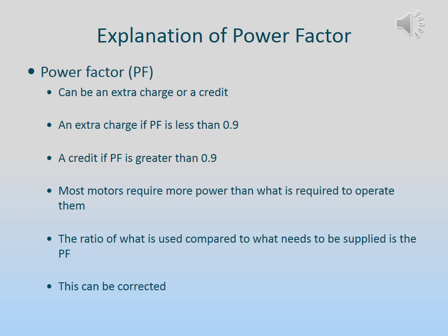Now there is some debate about power factor correction capacitors actually saving money. So let's look at the math formula and see for ourselves. Go back to the formula for calculating kilowatts. If we increase the power factor in that formula, then we have to decrease the amperage by a greater amount to save energy. So if we are going to increase power factor 5%, then we are hoping our power factor correction device lowers the amperage more than 5%.